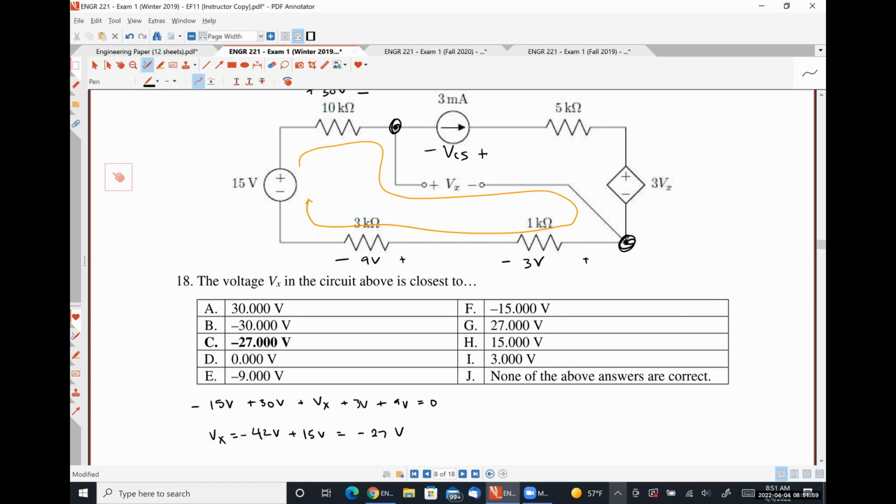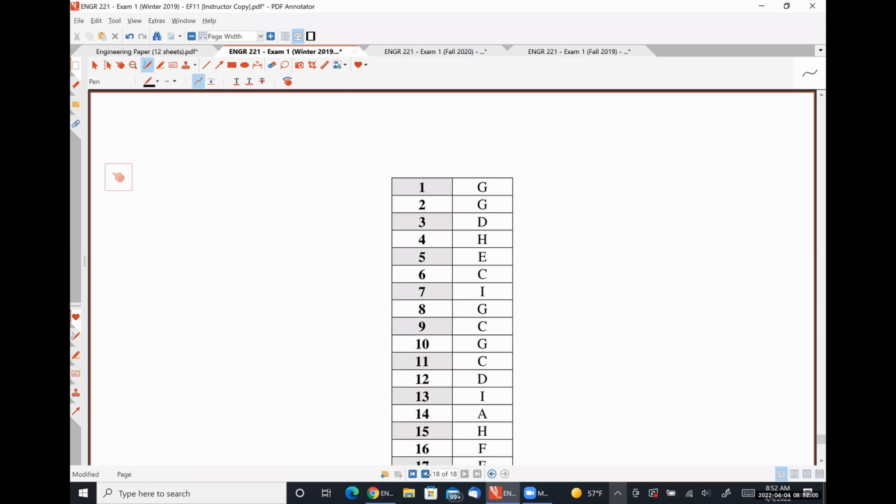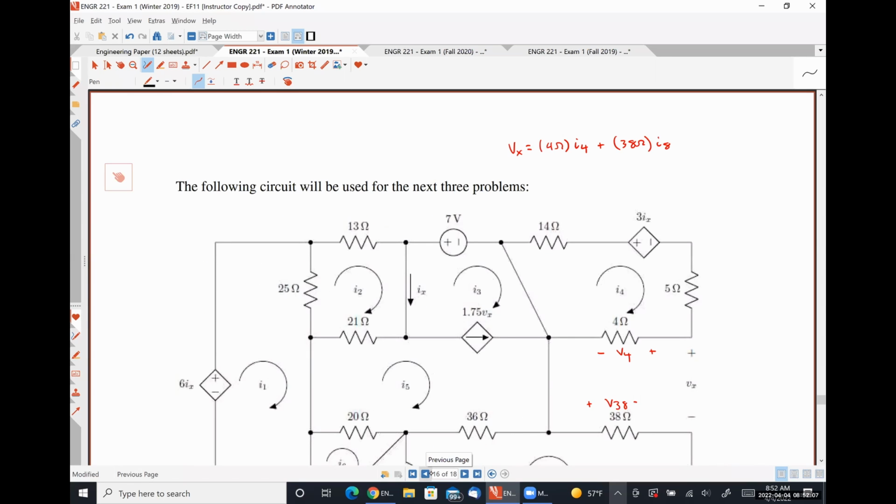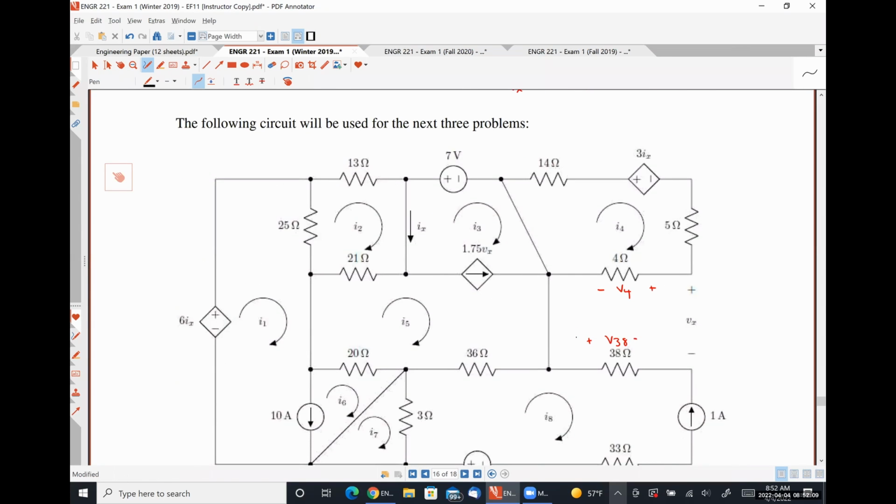So this kind of goes back to, let me see if it was problem 35 on this test maybe. Yeah, what we did here. This is a voltage drop. The Vx that we were trying to find was the voltage drop just between 2 points in the circuit with no current carrying path. And we just did KVL around things that carried current to figure out what was going on. The exact same principle we applied in that last problem.